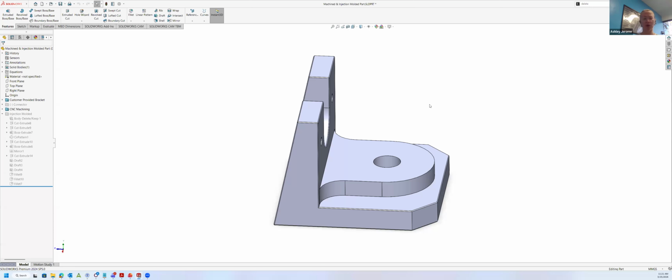So I think the order of operations here would be making something that can be built from a block off the shelf, deciding what are the easiest ways to go about bringing this down to size. And like you said in the previous slide, working with a machinist who can tell you, oh, that part right there, that would be really tricky.